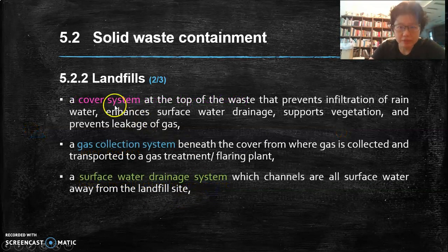And the third component is a cover system. Across the top of it, remember the first few slides we saw the beautiful completed landfill that we saw in Belgium and in Georgia in the States. There's a nice covering, whether you cover it with high-strength polyurethane so that no water will actually go in and cause more leachate to be produced, more toxic juice to be produced, or you have nice turfing covered with soil and vegetation, so that the surface runoff, precipitation coming from rain, will not excessively infiltrate into the landfill and cause more juice to be produced, the leachates.